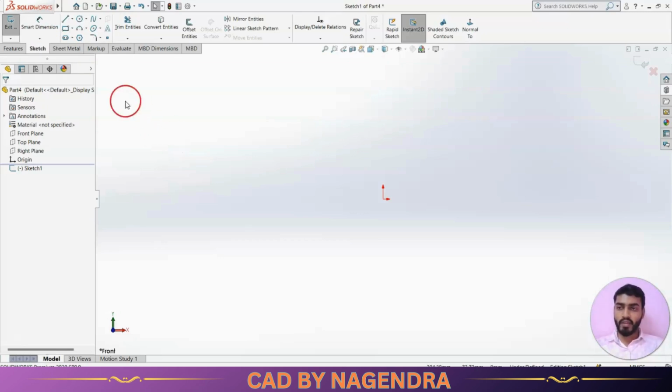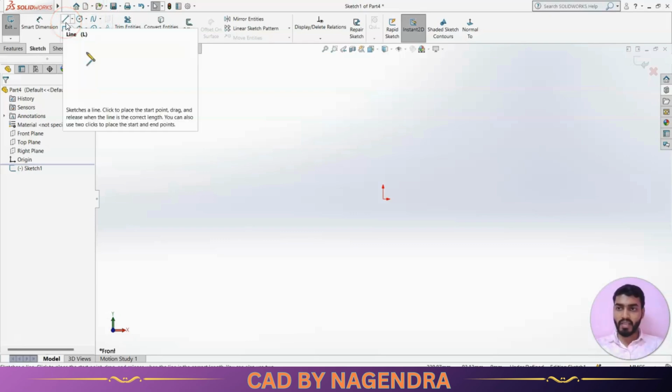Then next to that, we are having here profiles. First profile we are having here line. Let me click on line. As you can see, preview also will be shown in a pop-up how to create a particular line. Now shortcut key also it is highlighting as L. Instead of selecting here directly, if you use shortcut of L, we are able to create line profile directly.